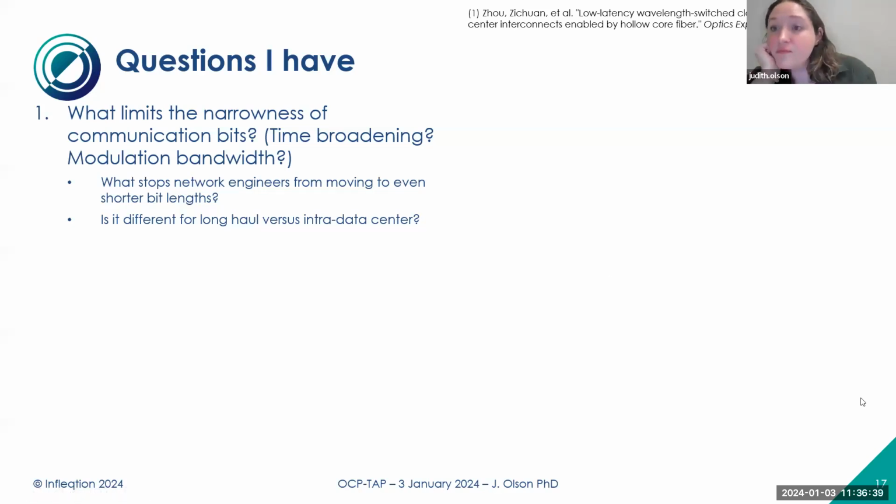Modulation problems are detection problems. So, yeah, it's both? Well, yeah, no, modulation problems are detection issues. So it's very difficult to integrate the result of your observation over some amount of time. So you have to allow enough time to be able to make a reliable measurement. And so that is kind of the laws of physics pushing back a little bit on modulation rate. Okay. And then does it also have to do with alignment of the timing between when you sample the signal? Like you need to verify you have it at some point and then sample within the middle so you don't end up getting bit errors. You sample it asynchronously.